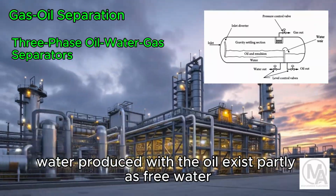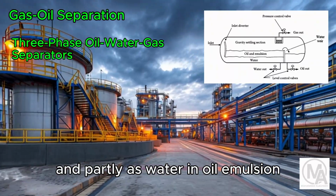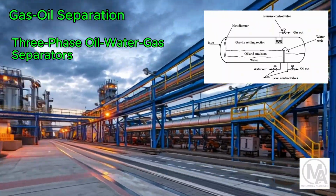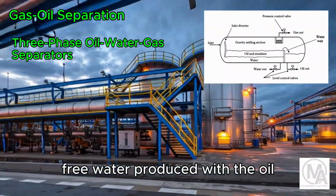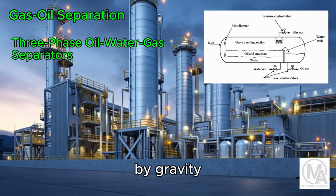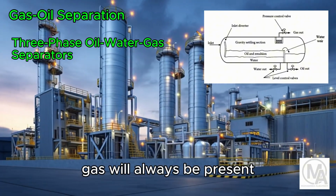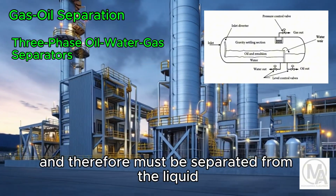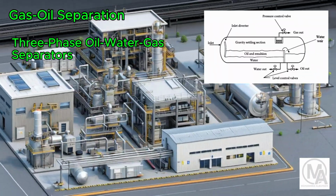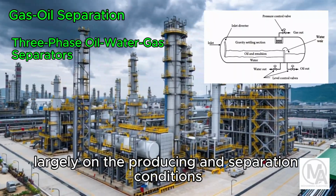Generally, water produced with the oil exists partly as free water and partly as water in oil emulsion. Free water produced with the oil is defined as the water that will settle and separate from the oil by gravity. Along with the water and oil, gas will always be present and therefore must be separated from the liquid. The volume of gas depends largely on the producing and separation conditions.